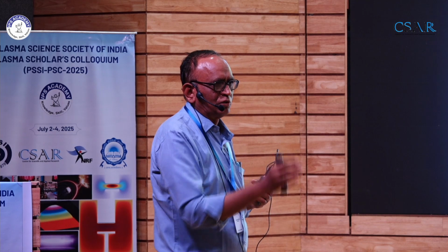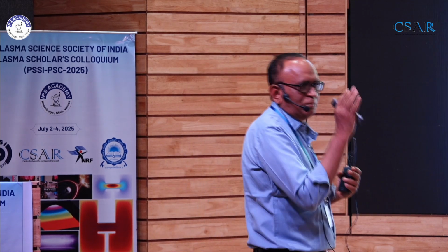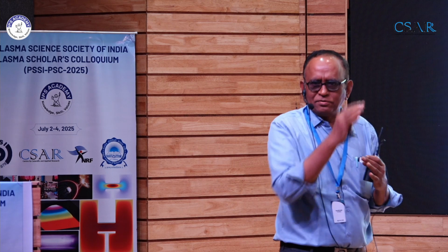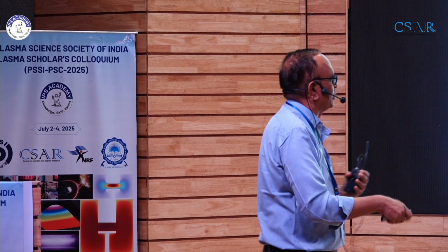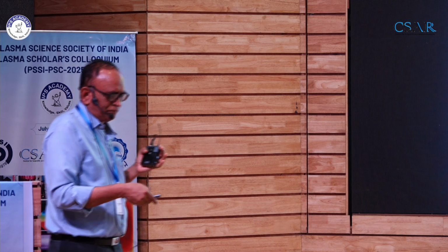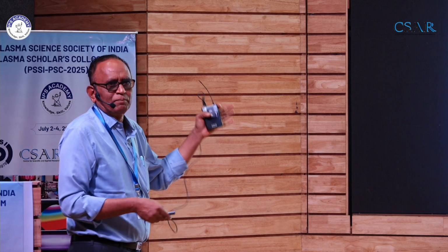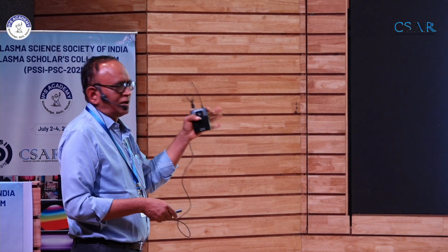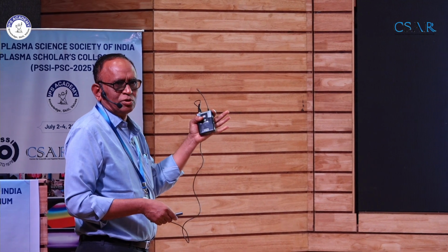If you are using a CVD process, they are basically impinging onto that substrate and helping you to get adhesion of the films, density of the films, and all those kinds of things. So I have explained how RF plasma is generated, what precautions you have to take, and you have to always make sure that your reflected power from the RF generator is near zero.